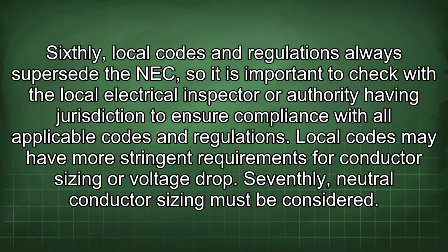Sixthly, local codes and regulations always supersede the NEC, so it is important to check with the local electrical inspector or authority having jurisdiction to ensure compliance with all applicable codes and regulations. Local codes may have more stringent requirements for conductor sizing or voltage drop.